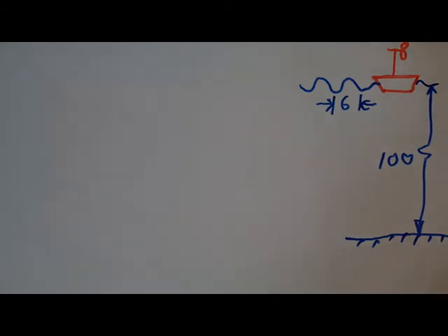To do that, we're going to use the dispersion relation, which relates wave number to frequency. Now, that is a relation which has the hyperbolic tangent function in it. That's a little bit complicated to evaluate, but we do know we've got the two approximations, the shallow water approximation to the dispersion relation and the deep water approximation. It's a pretty good guess that in water this deep, we're going to be able to use the deep water approximation. But let's first check, just to make sure.